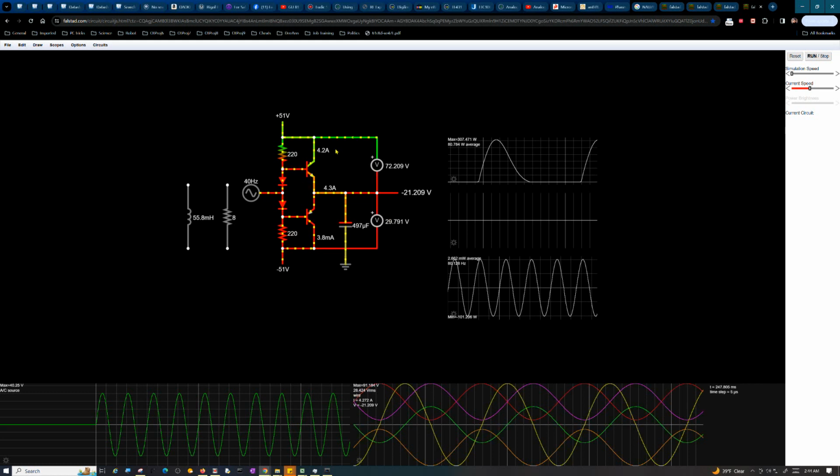Now the opposite is true, but this transistor first has to charge this thing up to ground before it can start charging it above ground. But again, that's when maximum current is going to occur, when the voltage across this capacitor is highly negative. Uncharged capacitors, for example, act like a short circuit. That's a way of keeping in mind why current leads voltage on a capacitor, because you have to have a really high current.